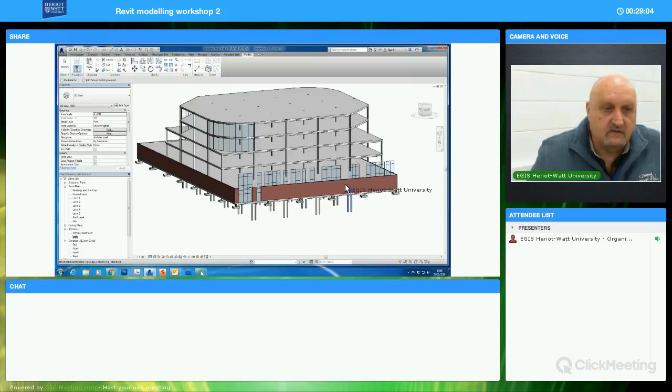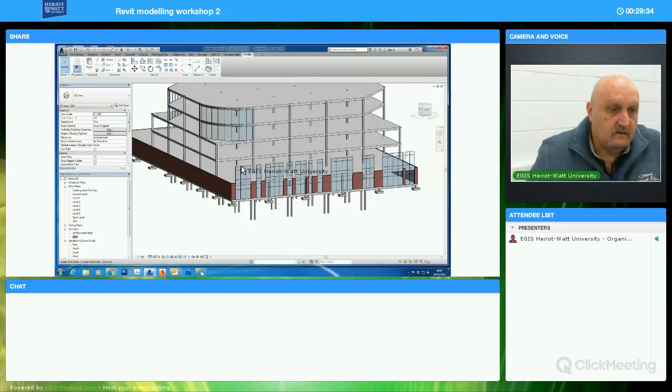I won't do them all on each side of this building because, again, if you can see it once and do it once, then you can do it with them all. Makes no difference. And this is quite a common way of getting light into the core of a building, in this case into the perimeter of the building. I select these walls and I cut them all, and that's it. And I find the height, because I can bring this down. I'm going to bring that down and the wall will reappear above it.